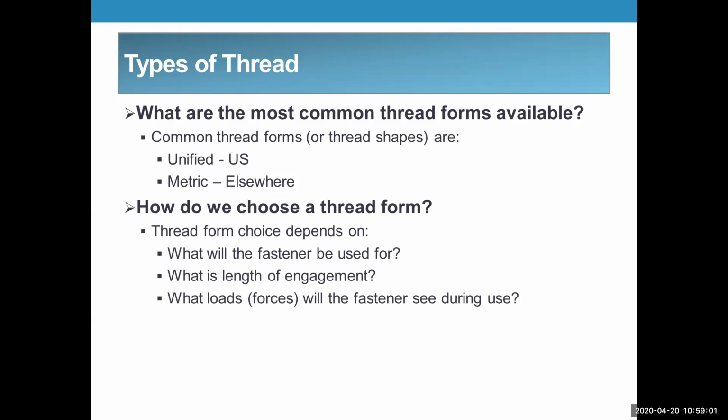And I'm being general here, but if those connections were bolted or riveted on the end, you wouldn't transfer, because the deflection is so small, any of that torsional load to those end connections. Even though it's riveted and bolted together, if you deflect the end a little bit, you're still only talking about a clamping force between the two members that are bolted or riveted together.